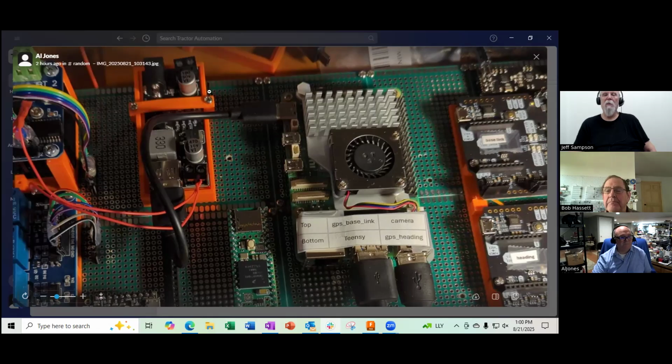And another thing to remember there on the Raspberry Pis, at least the older ones, the power light, if it didn't like the incoming power, it would blink or something. So that would be a quick visual indication if you're getting a power problem there. If you're running a desktop, they usually have something on the desktop that says your power is low, or at least the Raspberry Pi OS always had, they put a little lightning bolt up in the corner if your voltage is too low. That's the GUI, something you can watch there. And I don't know if the Ubuntu stuff does that or not. And I don't know if you're even running that. I think you were, weren't you?